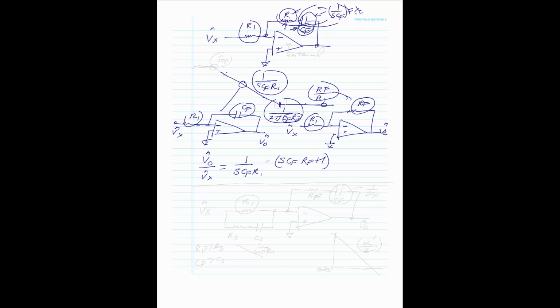Well, of course, the gain keeps on going up to infinity, but as we really know, what happens here is there'll be an op-amp gain limit, and that'll be the pole of the op-amp. That'll set the high gain limit, because no op-amp is going to have a gain of infinity. So that'll be the op-amp gain. But you don't see that in the external circuit. That's internal to this.